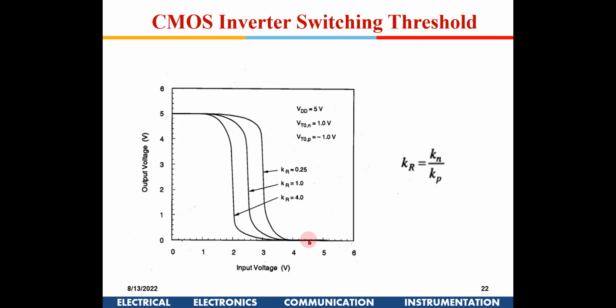But here if you see, as compared to the previous states, we are changing the width of the transistors only to move the VM, but otherwise the VOH and VOL remain VDD and 0. Is it okay with all of you now? Okay, so I have put only for static characteristics itself one full class, because these are very, very important aspects. So I am stressing this, and in case you have doubt, please ask me. Yeah, tell me.